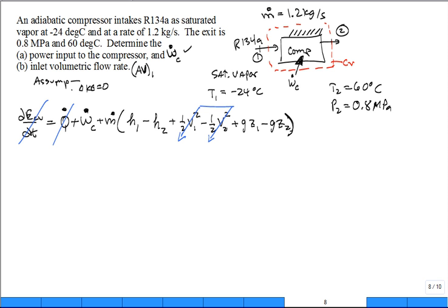How about the change in potential energy? And maybe you put over here that it is equal to 0, the change in potential energy, so that you kind of in a very compact way declared that is what you're going to be doing. You're assuming those. You mean that this W dot compressor is just the mass flow rate times H2 minus H1? That's it? Well, I switched the order of the H's. Is it good? Okay, I think it's okay.